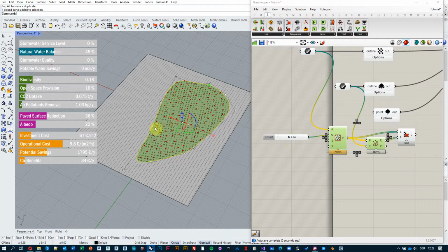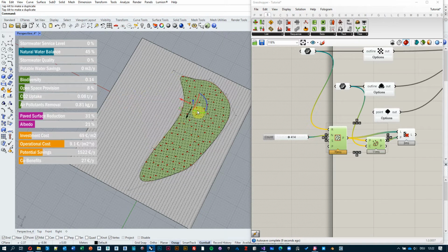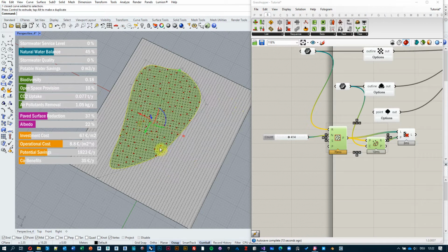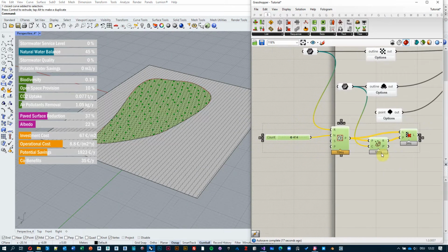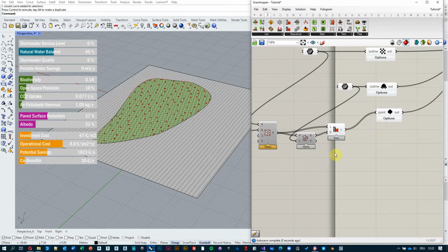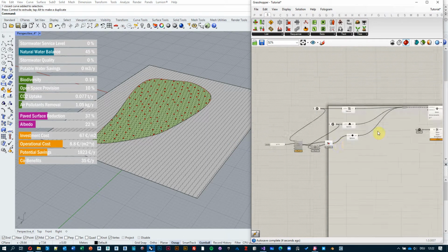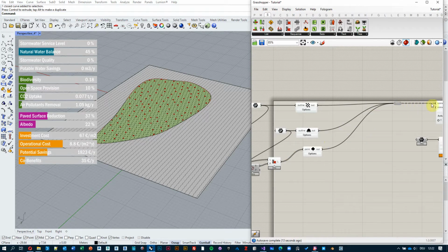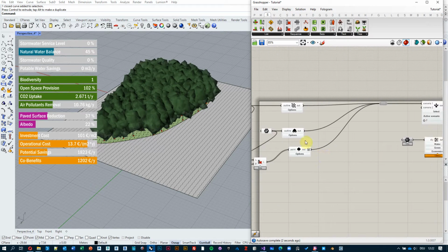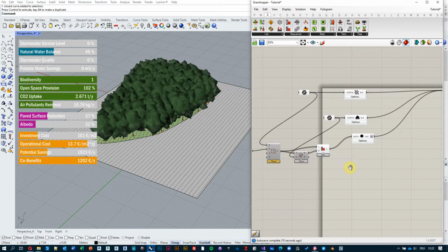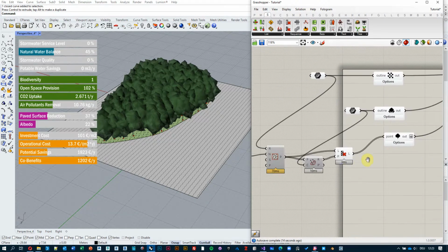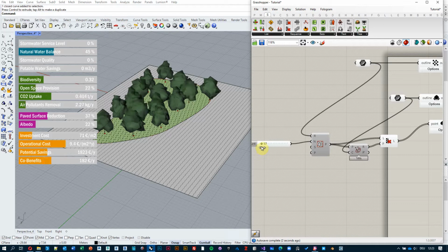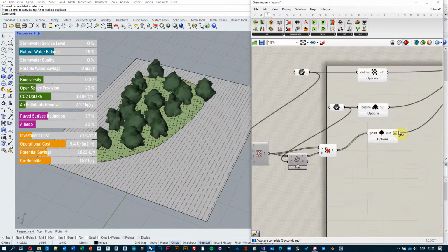Now you can see that we have a very flexible setup that allows us to change the density of the trees in the drawing, and it is always going to adapt, no matter how big the curve is or no matter its location. So now that we have all this prepared, let's connect all the dots together and see what's happening. Okay. One of the reasons why it broke right now is that it's generating a tree of data over here. So we just need to flatten the output from this component to make sure that a list of components is being fed into our scenarios. So again, right click, flatten the output, and we can see that it's way too many trees, that density is way too high. We can play with that, and very easily we have generated the inputs.